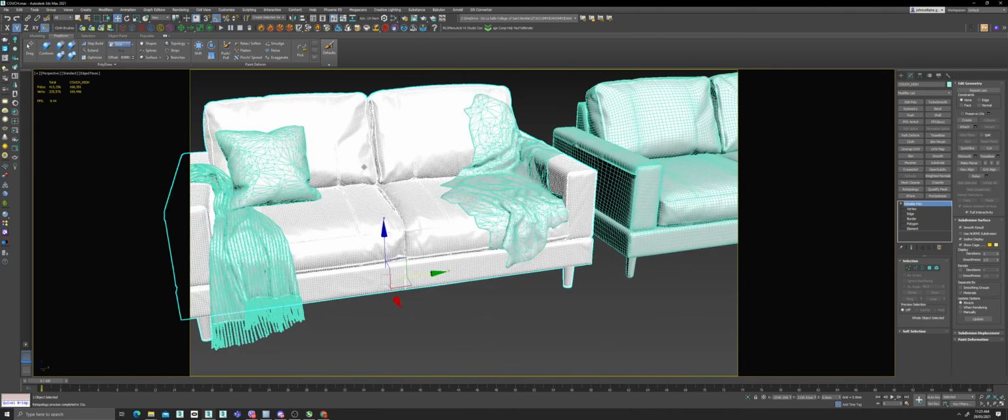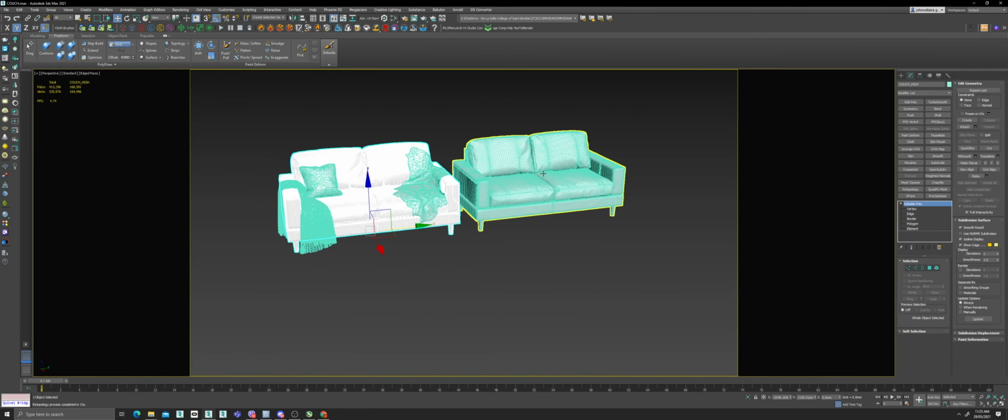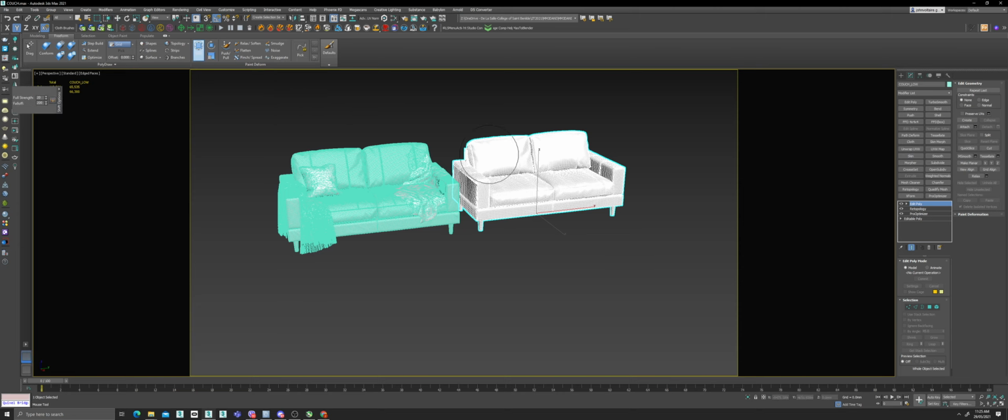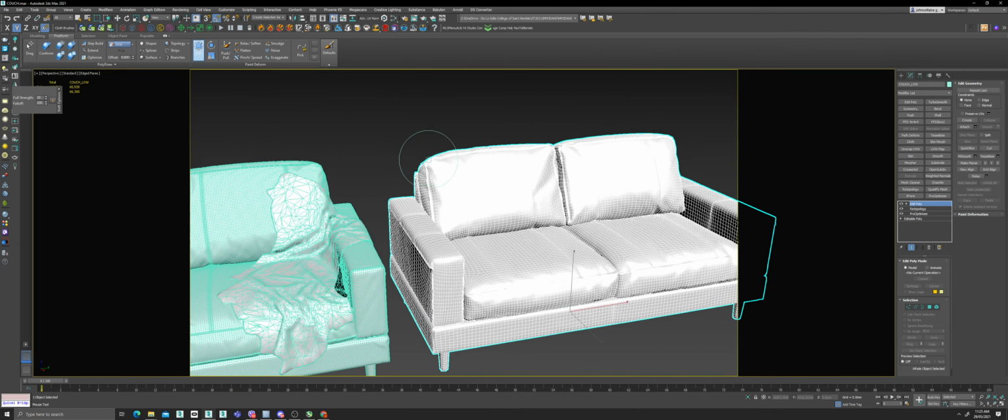For example, like this. Okay? So basically, apply the Pro Optimizer. And after you apply the Pro Optimizer, you're going to add the retopology command. Okay? And then, of course, you can now go back to Edit Poly, and then make some changes again if you want to. Right? Tulad yan. Madali ngayon mag-edit because your meshes are all quads.